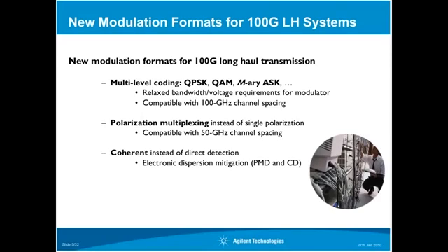The very interesting thing is that people are developing coherent detectors at the moment. Everything is about coherent reception. In general, it should be quite a hassle to have a laser diode at the receiver side, but it seems that the benefits are good enough that this can be justified. Coherent detection combined with polarization multiplexing and the new modulation formats gives very interesting performance features, and you will see a very high tolerance against chromatic dispersion CD, and PMD.